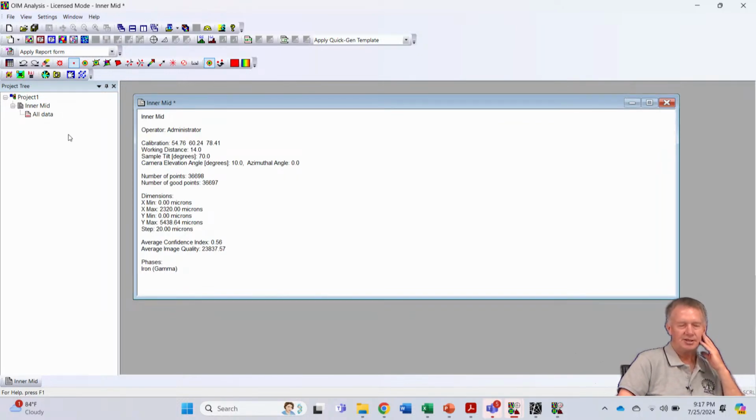All right, so this is a wire arc additive manufactured stainless steel. And actually what happened with this one is we started off with a little bit of carbon steel, just low carbon steel, a donut shape, and then we put stainless in the middle, and then we put donut shape again and stainless again. So we went back and forth between stainless and low carbon steel. So this is a structure that's in the center, right? It's like the donut hole that was being manufactured